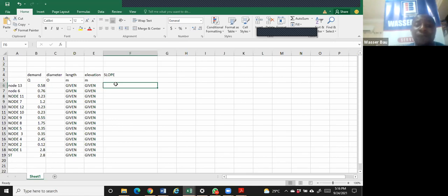But in real life, we are going to design the slope based on the difference between the elevation and the horizontal. Okay, so for this one, let's assume a slope of 0.5, for the purpose of learning fast. Are we together? 0.5, no units, but we assume a percentage. That means using my charts, this translates to 5 per mil.